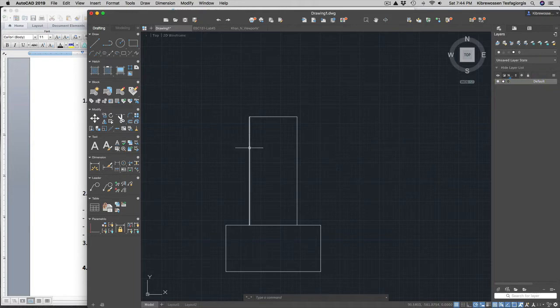But there are also more tricks with those grips. If I press and hold it, and then not holding it, press the space bar twice, then it changes to a rotational action. That means by holding the grip, I can rotate an object. Okay. Then what else?